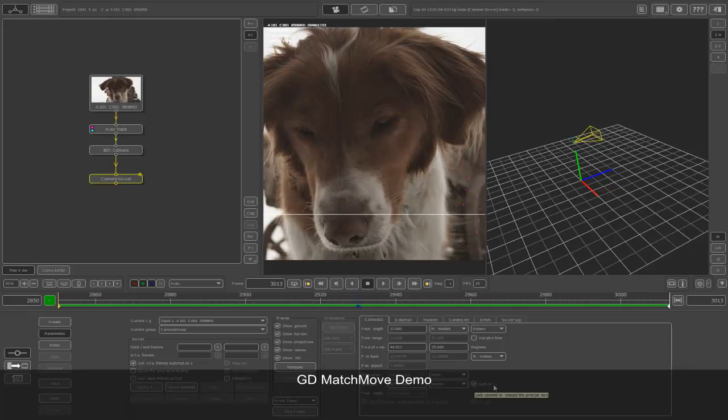My font settings have rendered out all the L's and I's out of the view, so that might be a problem. This is actually lock roll. Then under rotation, I don't want any jerking rotation movement, so I'll set it to low smooth, so that the camera motion is automatically smoothed out.